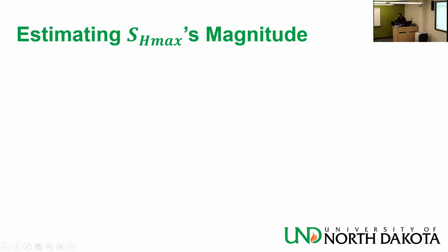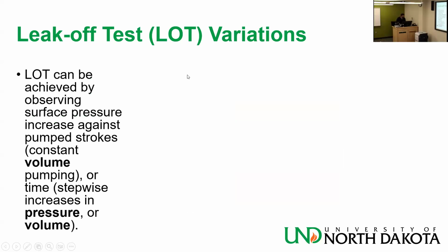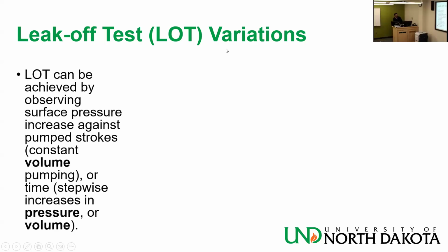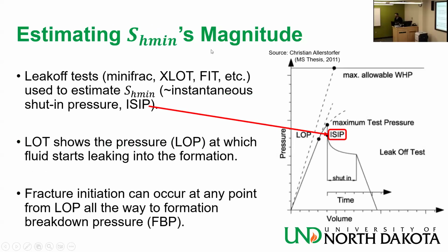Formation integrity test, I need to take it out from that list. Formation integrity test, it could be this FIT. It's a bad idea I put it there. I will take it off. Formation integrity test is not exactly leak-off test.